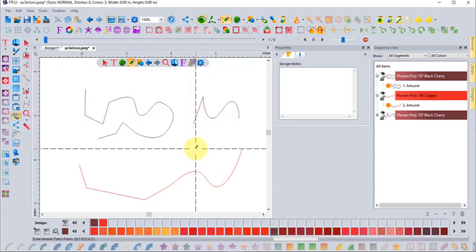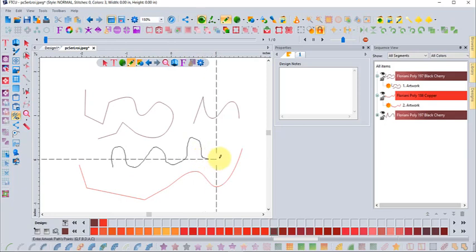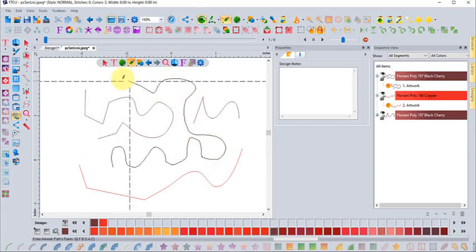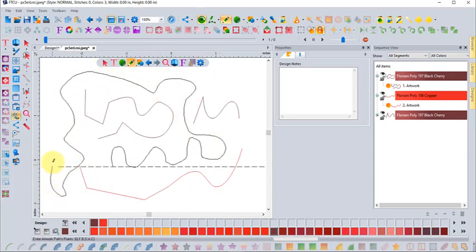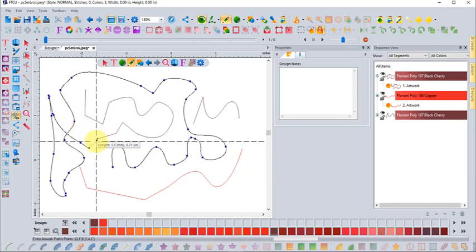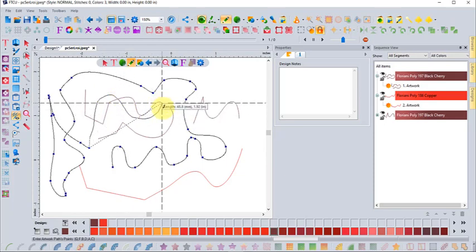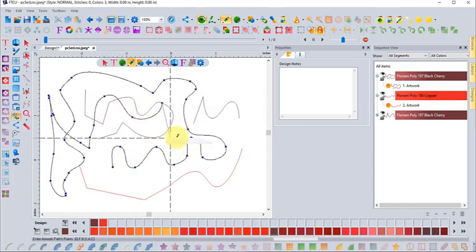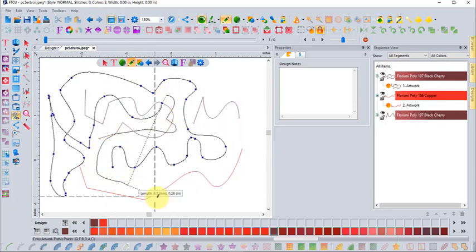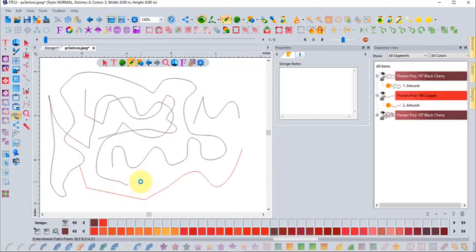When you choose the pen, then when you click and drag, it draws as you move your cursor. So kind of like a pen, it's more of a freehand drawing mode. If I go out and hover and then start drawing again, I can get to a corner, into a point, and not be curvy. But essentially you click and drag to draw the line. And you can take a break while you're drawing. See, I'm still connected to my last point, and I can draw some more, and I can rest my finger, and I'm still connected. And if I'm done drawing it, I simply right click on that.